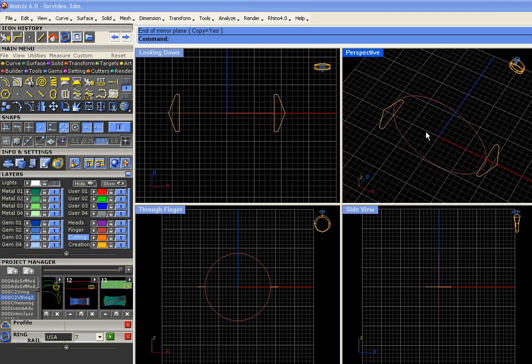However, we're going to need these later on because we're going to do some fancy stuff to this surface, and we want to make sure we have a good copy of these profiles to use later. So it's a good time to job bag everything anyway. Now we'll just grab these profiles, run duplicate in place, and put the copies, doesn't matter which ones, onto another layer color and just turn them off. Okay, just don't forget they're there. Another thing you can do is to grab them and just put them in a job bag. Make sure you have a copy for down the line.